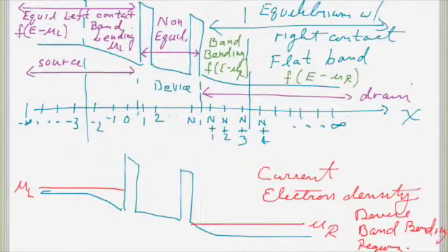In a real device simulation, you would have to be iterating this with Poisson's equation to get the potential correctly. So you'd be calculating the charge, sending it to Poisson's equation to get a new potential, and iterate until convergence. And to do that, you need the electron density anywhere where there's potential variation occurring. Okay, so this is what we want to calculate.